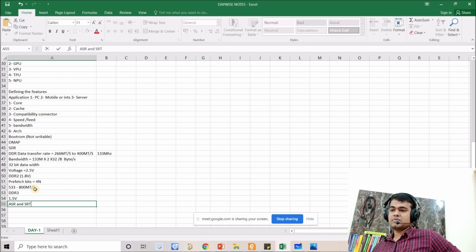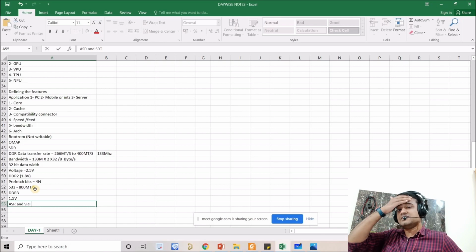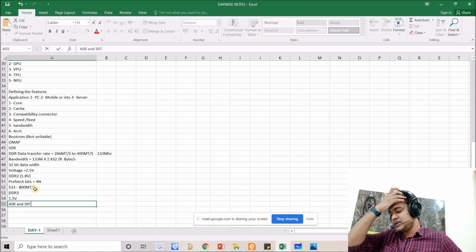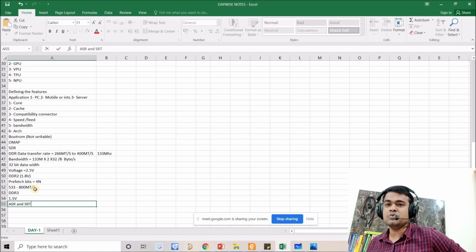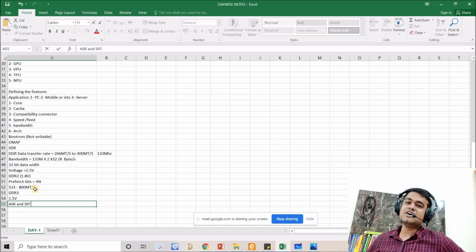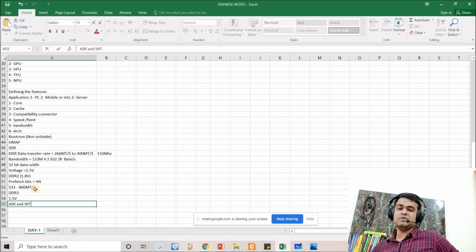Anyone? I would say to clear up the memory, but that's just a guess. Yeah, I mean, refreshing a RAM will clear the memory. That is one thing. But here the purpose of refreshing a memory is power consumption, or you can say heating. So you can relate that with switching regulators. When we have switching regulators, we are able to transfer a high amount of current as compared to linear regulators or LDOs, right? So similarly, they have introduced this feature to lower down the temperature, right?